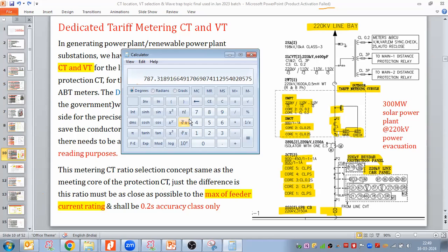No, that is okay. That is the standard design 900. That's not an issue. But still, we have to consider the power factor for this one, since we are using inverters. Inverters have the lagging power factor, and even the PV cell doesn't come with the unity power factor. There are certain PV cells with 0.96, 0.97. We have to check it. Raghav sir, correct me if I'm wrong.